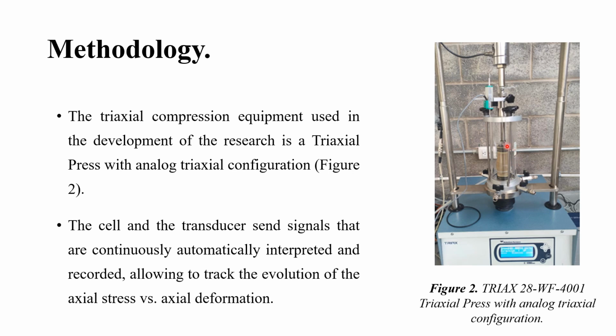It is a cylindrical soil sample, 10 centimeters in height and 5 centimeters in diameter. Of course, there is no confining stress because we are going to subject the soil to a simple compression test, and this configuration allows us to reproduce the stresses that we want to know.